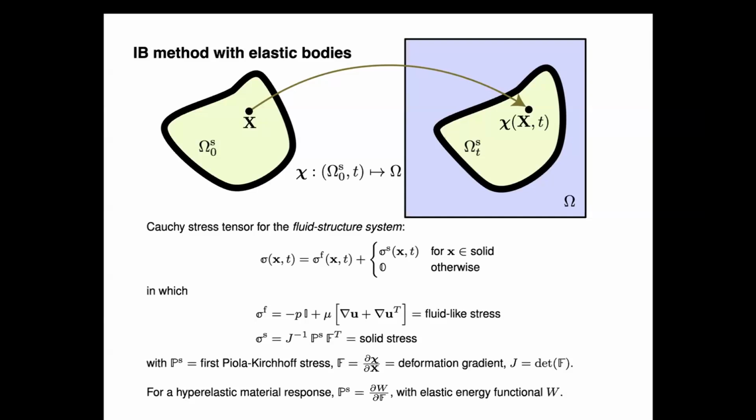We've got fluid-like stresses everywhere. And for simplicity, the fluid-like stresses look like stresses of a viscous incompressible fluid, described using the incompressible Stokes equations eventually. And then in the solid region, there also are solid-like stresses. And the solid-like stresses come from the constitutive model that's describing the elastic response of the structure.